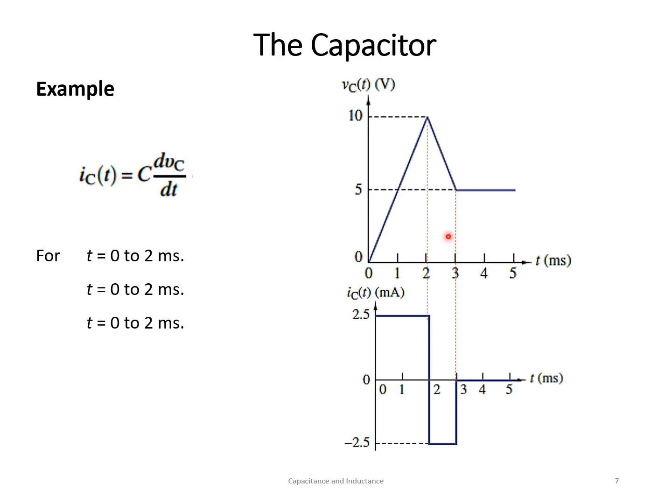You know, dV by dt is negative in this case, as the capacitance is always positive and dVc by dt during this time segment is negative. Therefore, the current will be negative. I haven't mentioned the capacitance in farads. See the textbook for the capacitance in this example, and you will see that the current is minus 2.5 amperes.